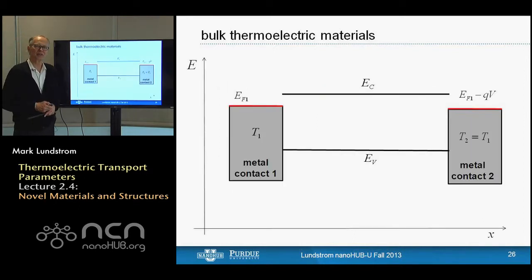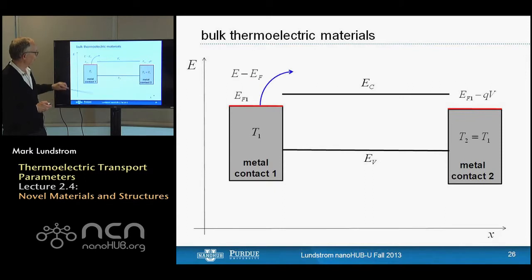Now, what happens in the thermoelectric device, which in the end mathematically looks very similar? In the thermoelectric device, electrons have to hop from the Fermi level in the metal up into a state in the conduction band. So we filter out the electrons that don't have enough energy to hop up there. The Peltier cooling occurs because of that energy filtering process at the contacts.